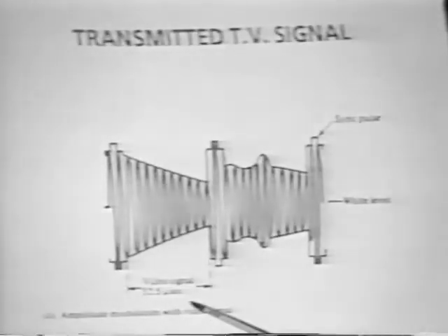Let's look at another example and go back to the example of a TV signal that we mentioned in one of the early sessions. As we talked, a TV signal typically is about 4 or 5 megahertz in bandwidth to construct the entire signal. And the example we showed, we saw that this bandwidth was from 0 up to about 4 or 5 megahertz. That was the portion of the spectrum used by a TV signal. Now, if we're going to multiplex TV signals, we would like to use more than one of these 5 or 6 megahertz bandwidths and spread them out across the spectrum. And this slide shows how to do that. Do it by using amplitude modulation.